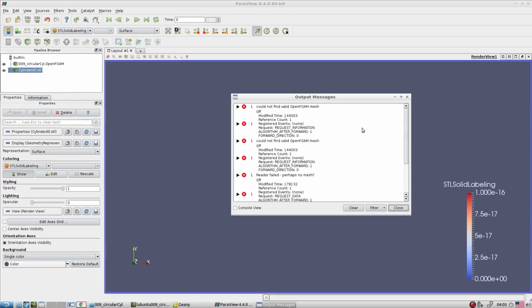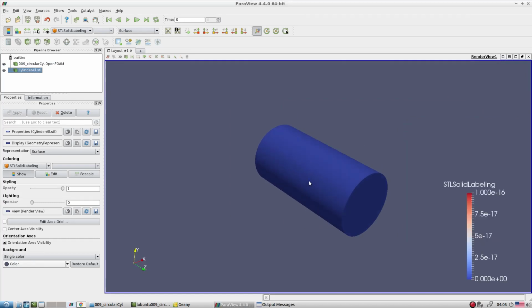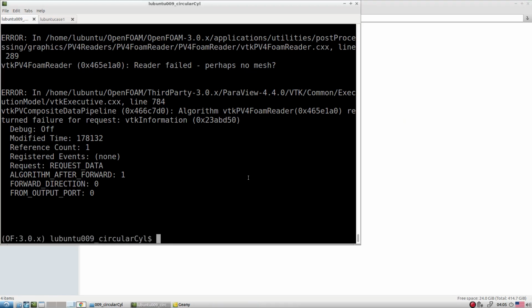So this is the cylinder, and we require the two-dimensional mesh for this. Wherever you require the two-dimensional mesh, it is not necessary that the entire cylinder, that means the Z direction, is covered within the block, because we want only one cell thick mesh in the Z direction. So here our blocking strategy is something different. Let me run the blockMesh file.